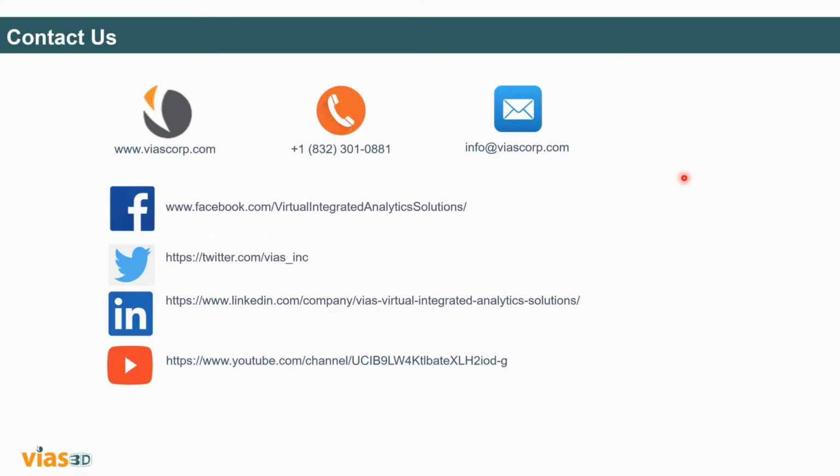Yeah, the optimizer can definitely be used. But before the optimizer, I would recommend first using the parameter sweep. With the parameter sweep, you understand which variables are mostly affecting your design. In a design there can be 20 variables which can be affecting it, but you have to choose the 4 main variables which affect it the most. You can achieve that by running a parameter sweep. Now you have chosen 4 candidates, and you can use those 4 candidates in the optimizer. Then the optimizer will give you the best result.